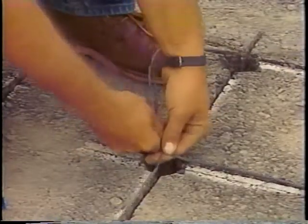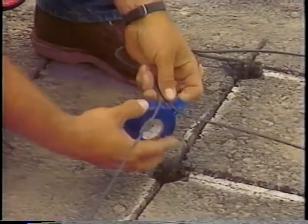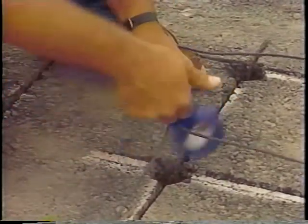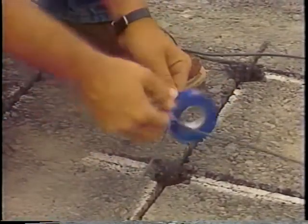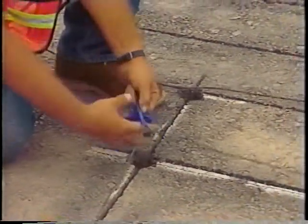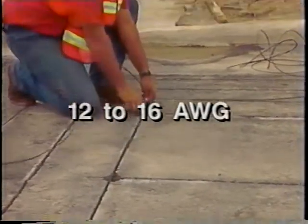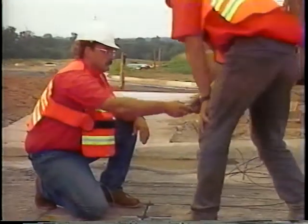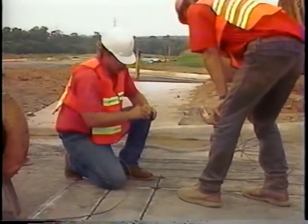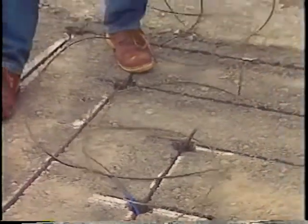Many contractors have developed their own wire installation techniques and shortcuts. It is important to inspect these procedures during installation. If a wire is damaged during installation, it should be immediately pulled up and replaced. The most commonly used wire size ranges from number 12 to number 16 AWG. In our example, we are using number 14 AWG wire. Stranded loop wire is more likely to survive stretching and bending.